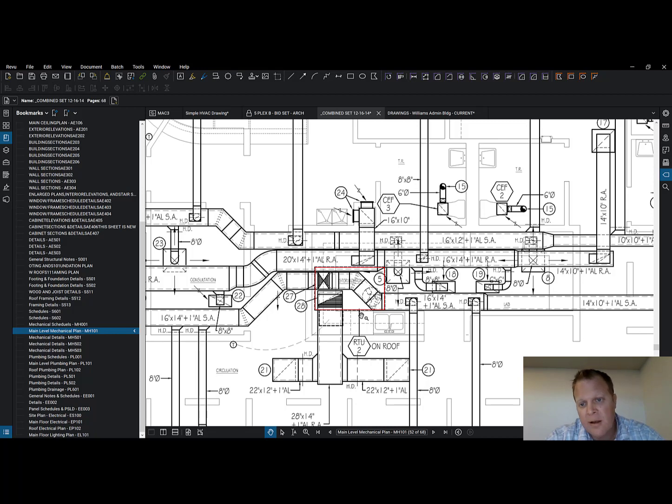All on one side, and then it's got a blower, and it's got the probably gas-fired furnace on the other side. So those are some utilities we need. We need gas. We need power. We don't have a condenser somewhere else, so we don't have to run refrigerant lines to it because it's all in one, right? So we don't need the condensing refrigerant lines. It's all inside that. We have to cord.